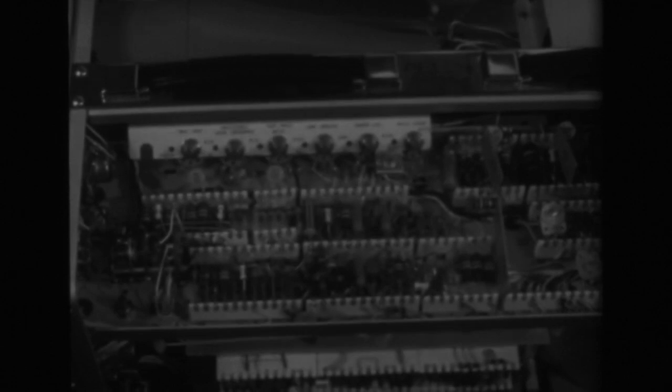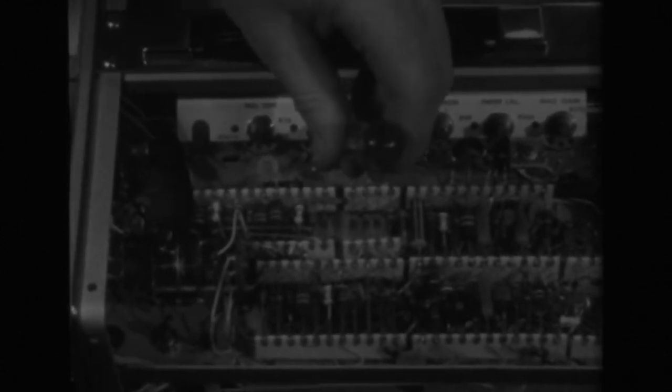As the next step in our adjustment procedure, let's preset the trigger circuit adjustment pots to about mid-range. First, the triggering level centering pot should be set somewhere near the middle of its rotation. The slot will be vertical in this particular scope. Next, the trigger sensitivity pot should be set in about the middle of its range. The slot will also be vertical for this scope.